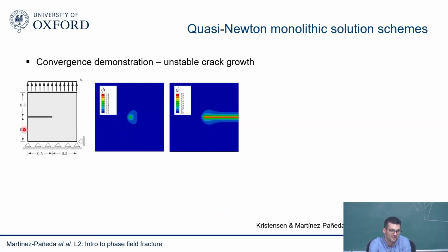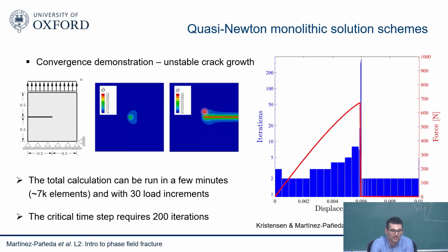So this is a very classic example in phase field. Your material is linear elastic. You have a square plate with a crack, and you pull. This is linear elastic material, mode 1, so the crack is going to grow in an unstable way. Just sudden crack growth, mode 1 fracture in a brittle material, right? Unstable crack growth. And you see it here, right? So I'm starting to load, and then eventually, pop, my phase field becomes equal to 1, and you get complete failure. So here what I'm plotting is, first, look at the red at the right side.